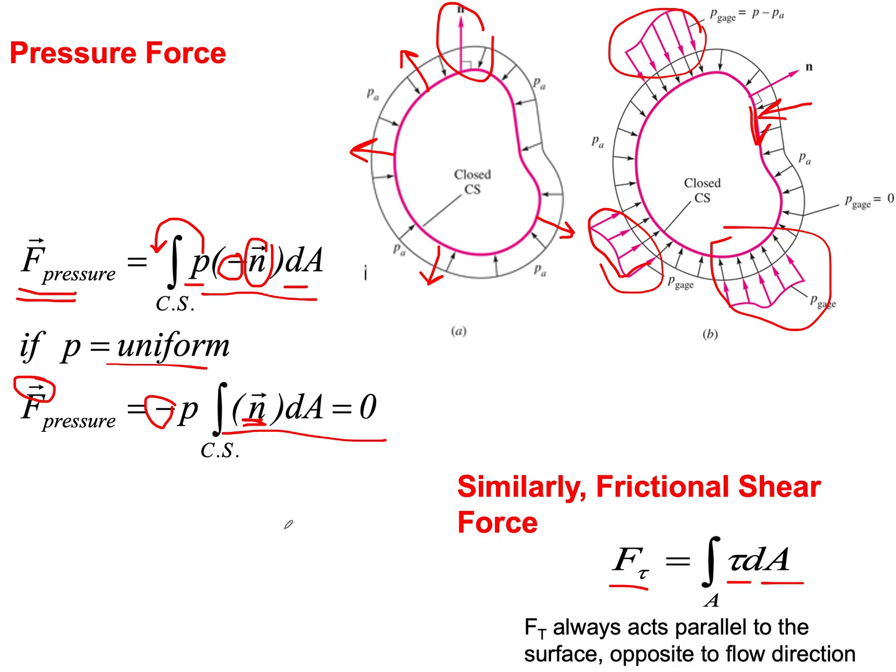One thing also to keep in mind is why would shear come into existence? It comes into existence because there is rubbing between fluid elements, and that happens when you have a faster fluid moving closer to a slower fluid. And in this case, that's what we call a velocity gradient. When you have a velocity gradient, if you look at this fluid element and this fluid element, they're rubbing shoulders against each other. This one is going past that one, and that's creating friction between them, and similarly between this fluid element and the one beneath,